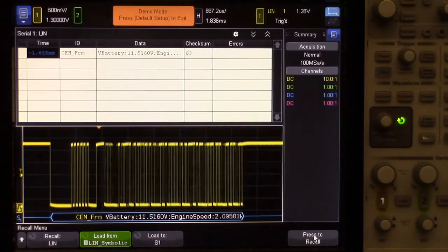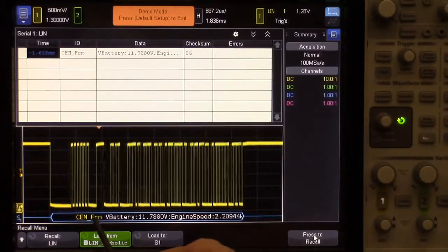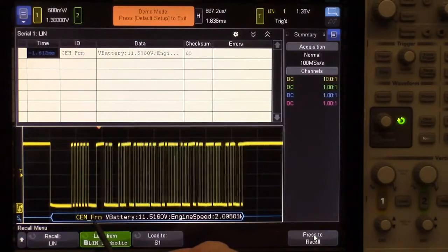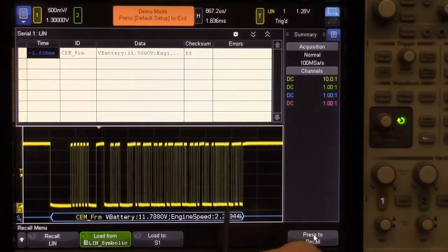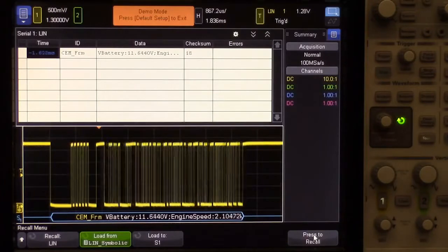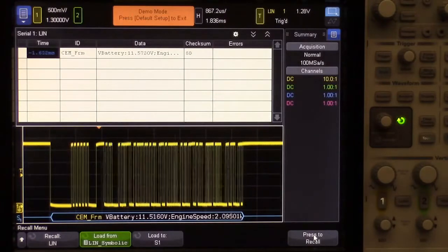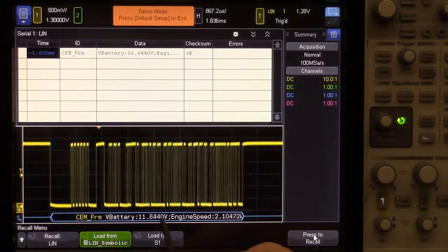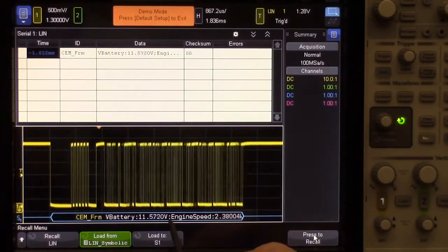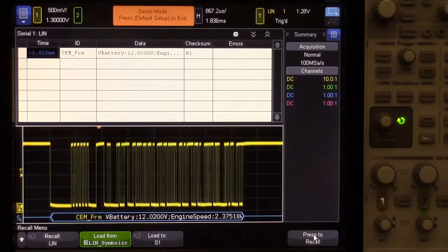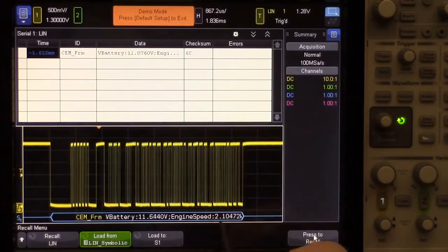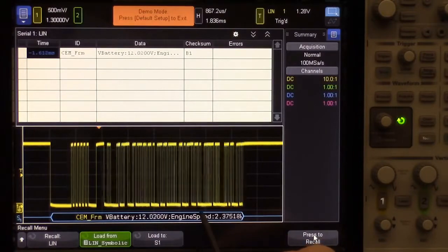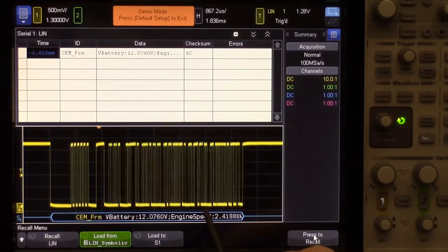So what we saw before as frame ID 30 hex now has a name, sim_frame, and then all the hex data has been demultiplexed into what's called signals with signal names. So here we see V battery and then values and units. Now notice here we're only seeing 2 signals. There are more signals in this particular frame. We can drill into this. Let's do that now.